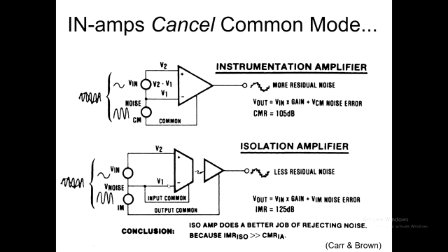In an isolation amplifier, there can be an element of that subtraction still occurring, but the isolation mode signal, which sits across between the two notional return paths, the grounds. I use the term advisedly because the grounds are only reference points for each of those two sections. It's not as if they're forming a common ground. The idea is to make a separation there, and the isolation mode and common mode signals between are rejected by attenuation.